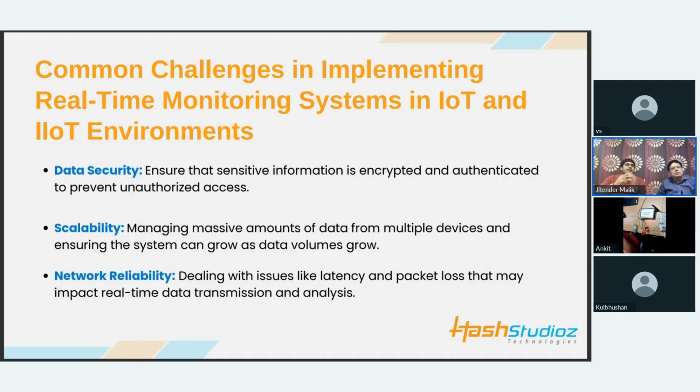Then again, a question from Venkatesh. Yeah. So, brief about MQTT. We are transmitting over a TLS secured MQTT server, which is basically the de facto industrial standard for transmitting data, small or large size, onto the network when you're talking about industrial automation.